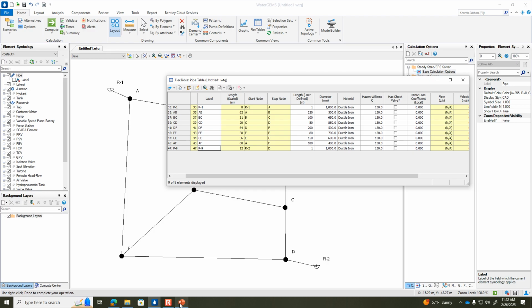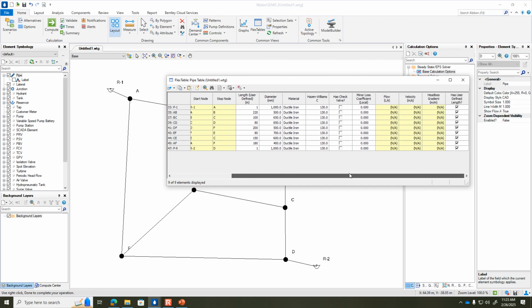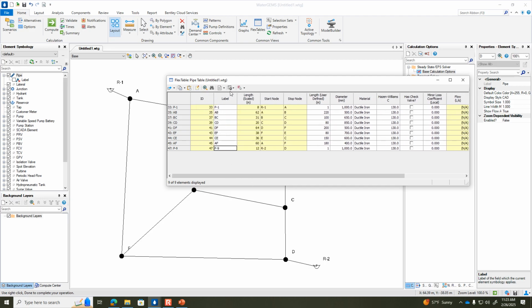In the handout I gave you, it said that each of these pipes has an equivalent sand roughness of 0.3 millimeters. So it's got Hazen-Williams C values here. Don't take that as an indication that it's going to use the Hazen-Williams equation necessarily. We previously defined Darcy-Weisbach, and it's going to use the Darcy-Weisbach equation. It just has a lot of different properties here. And by the way, these aren't all the properties that you could have for the pipe. There's more things that we could include.